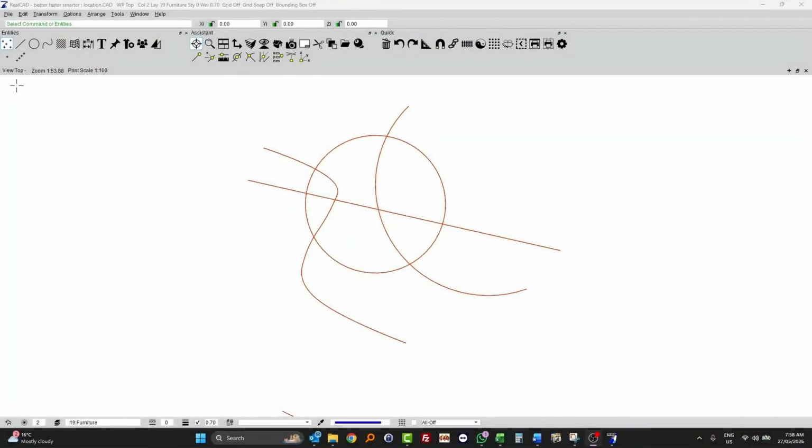In this example, I'm going to insert points rather than lines, and I'm going to use the intersection tool. Normally, you would only need to hover your cursor over the intersection and you will see a cross at your cursor's location, which is exactly the same as what we're about to do. But sometimes, because there are so many lines in the way, it's not sure which one you're actually working on. So you choose the intersection tool, and then you come across with your diamond. Once you see the diamond, you know that you found the right location.